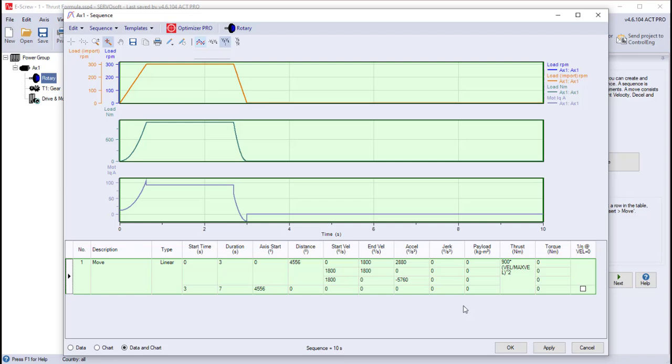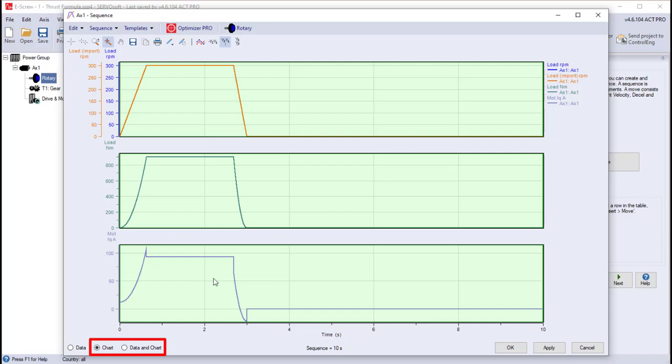I'll confirm this by selecting the calculated profile in the legend to make the line thicker behind the orange trace profile. First, I'll make the chart bigger by selecting Profiles Only. This is an important step to confirm the programmed and actual motion profiles match. Now let's import the motor current trace to confirm all inputs such as load inertia and thrust load match the actual measured application.